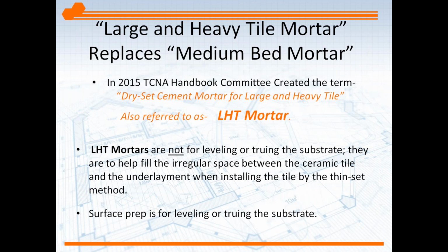So what changes with the mortar when we talk about large format tile? We had a term that was bouncing around and we were using originally when we created new mortars for large format tile, and that was a medium bed mortar. And that was effective, but I even got a lot of questions on the medium bed mortar terminology. A lot of design firms believed that meant create a mud bed. We need to create a mud bed to put in large format tile. And that wasn't the case.